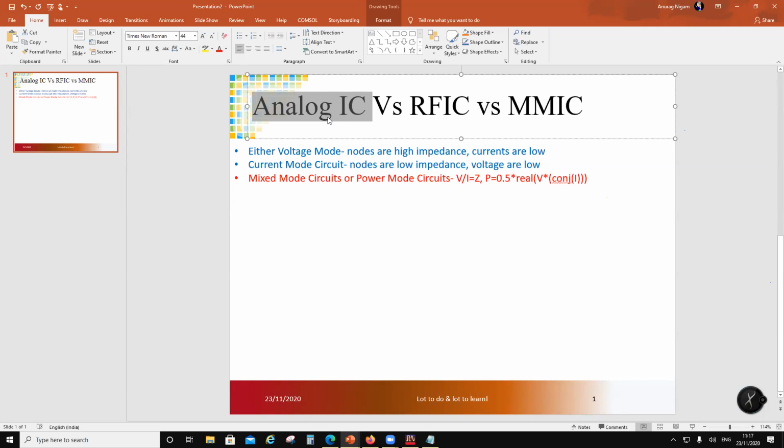So differential circuits you see everywhere. Actually, differential circuits you see here, here, here. But differential circuits have two advantages. One, the common mode noise is cancelled out. Second, the common mode input voltage range is large. That's why you do differential circuits. But then differential circuits have their own restrictions. The restriction is systematic offset voltage.